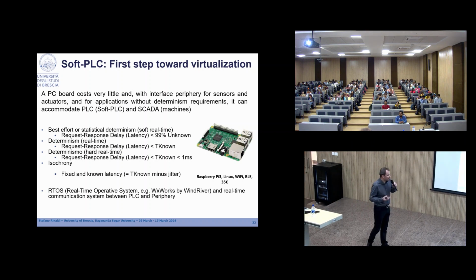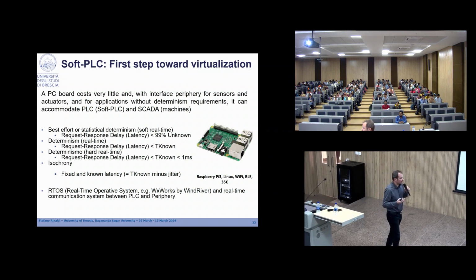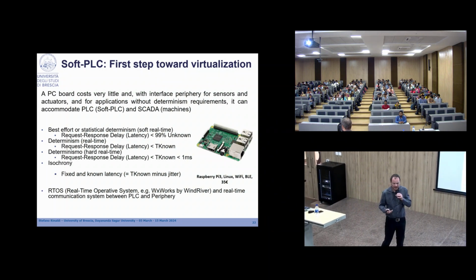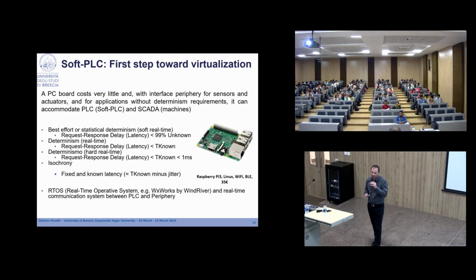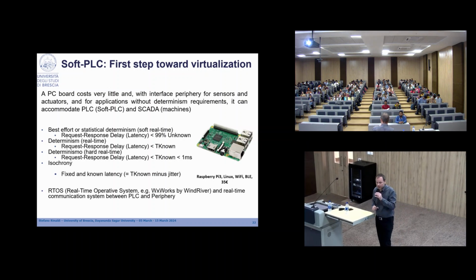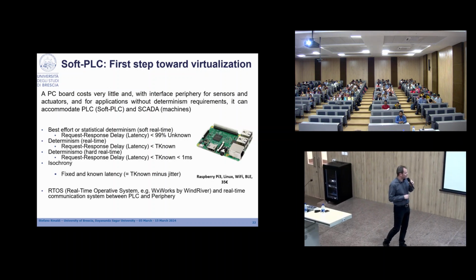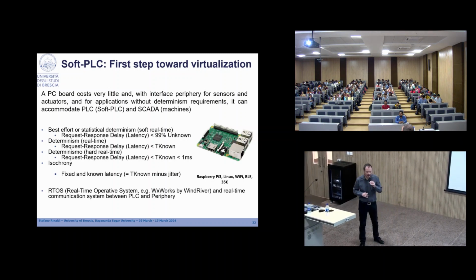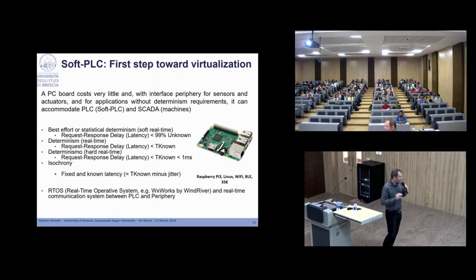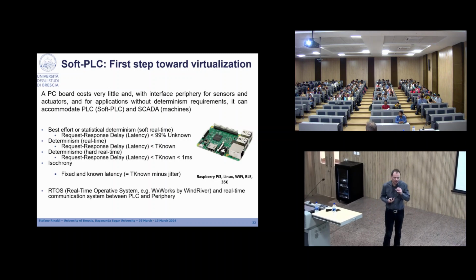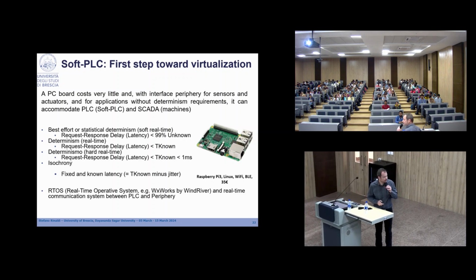So we can run a soft PLC application not on a traditional PC equipped with a traditional operating system, but only using a real-time operating system, like for example VxWorks and other operating systems. With an RTOS, we are sure that our PLC application is able to satisfy the real-time requirements.